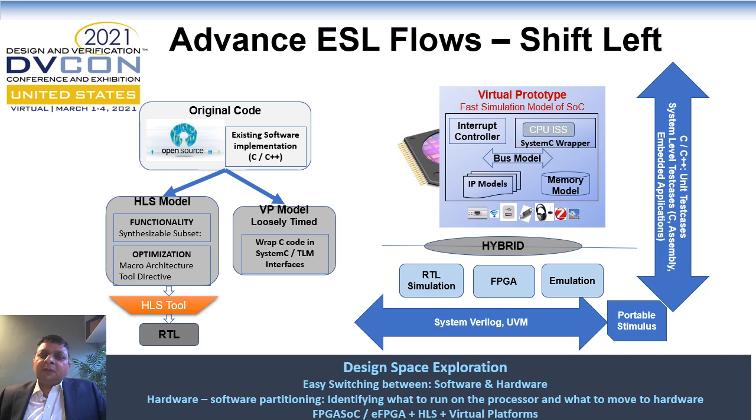We can further combine these with RTL simulation, FPGAs, and emulation to create a truly hybrid environment. And further we can create a verification setup which can actually flow from IP level to SoC level to system level.